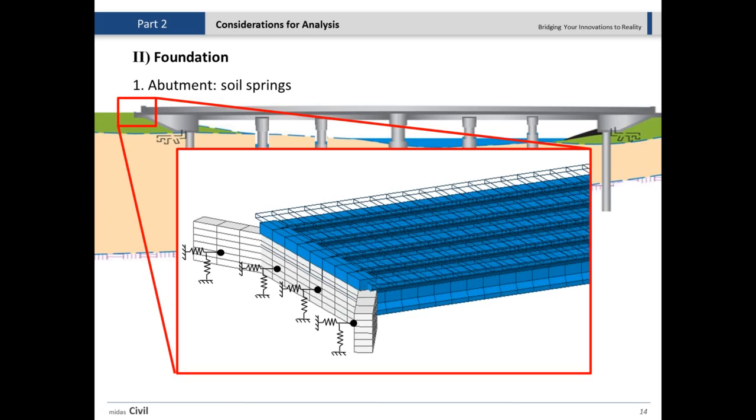because that gives us a more realistic response of the structure. Just consider that if you model the entire structure with a simplified method, where you ignore the abutment and just apply a simple support or a fixed support there, you are definitely coming up with some assumption, and that doesn't lead to an economic design, because you are doing the analysis on some other type of structure.